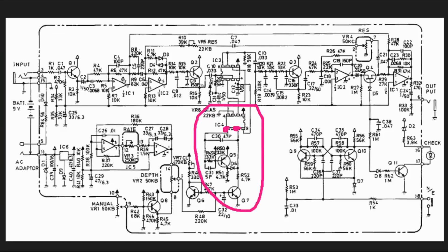So the delay time of our BBD is constantly being modulated through that action of LFO plus a bias voltage onto a variable resistor connected to the oscillator pins of the clock driver IC. And so when we put all of that together, we get this fully functioning flanger.